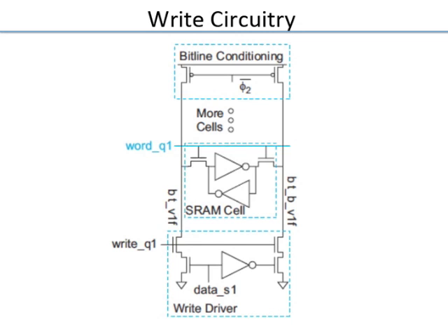So depending on the structures, if you have very simple structures, or very simple AND gates and so on, you still get things done, but the area overhead will be more. But when you do something more fancy, you will have to have a little bit more complicated control. But in the case of memory, area is always important. You really want as small an area as possible. So you cannot do all this timing generation in a separate place and generate all these signals.